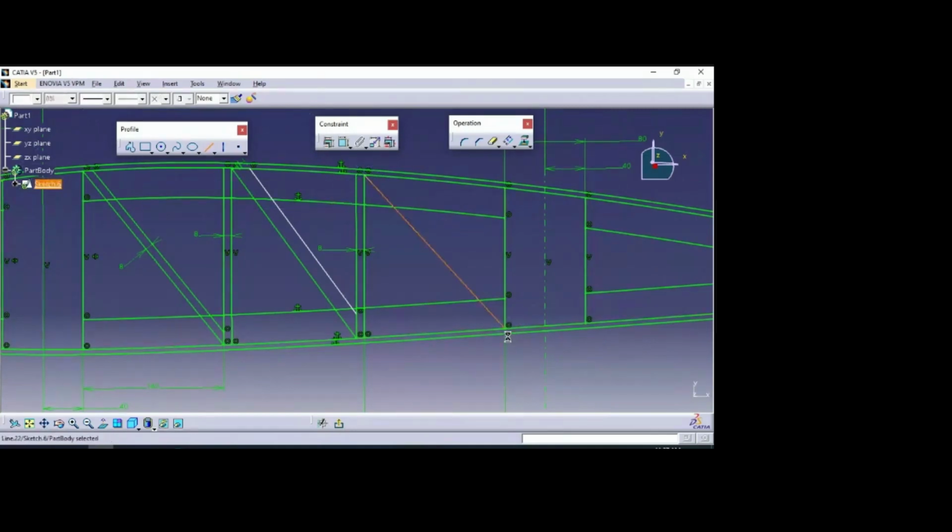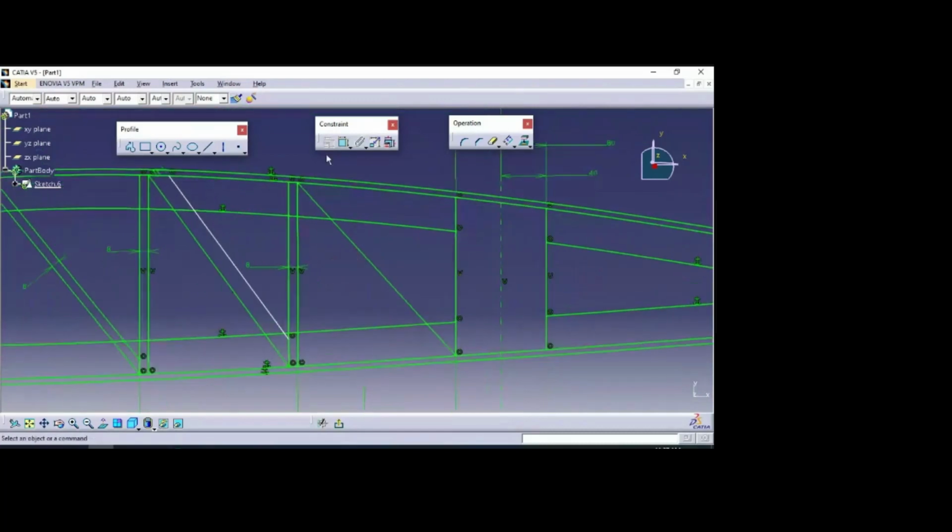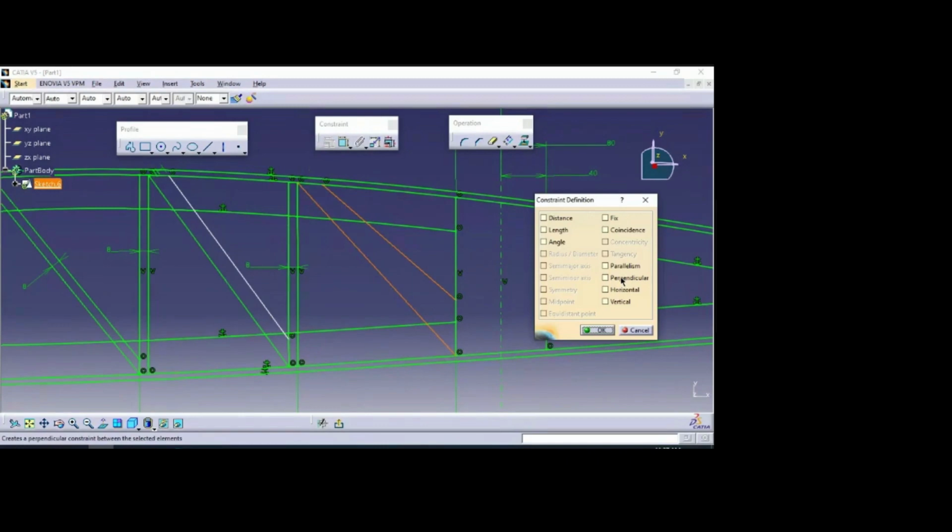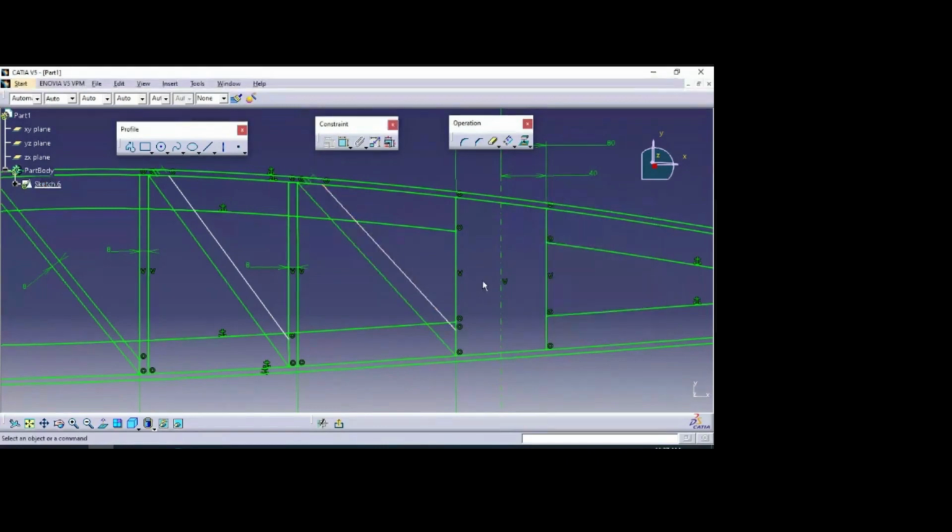For example, see here I'm drawing one line. The first line is no issue. The second line also, while creating, see, it automatically shows the parallel symbol in the center, coincident on the line. If it is coming like this, it is not an issue. Or if you couldn't pick, or it is getting some other parallel issue, that is an auto constraint issue, you can select it anywhere. Then select these two lines. You can give parallelism. Both ways you can give it.